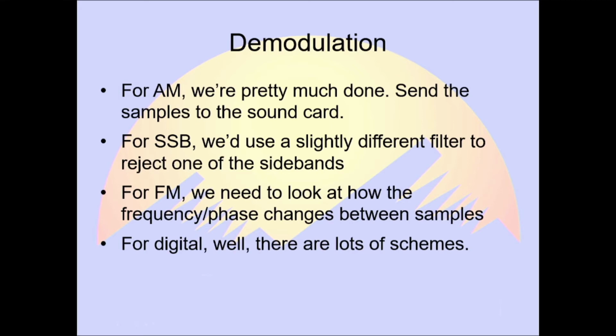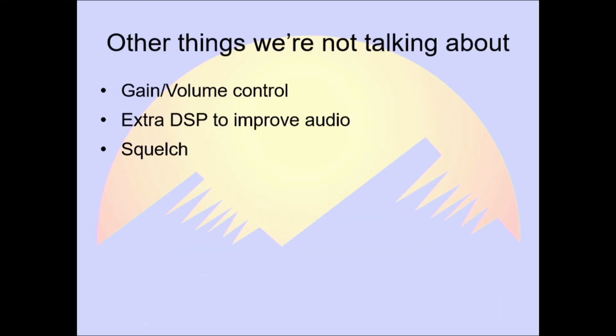So if you want to do it fast, you should go build a chip. That's what programmable logic is for. Then you can program your chip, which is actually very commonly done in SDR. Many of the higher-end SDRs will have an FPGA on the board so that you can do at least some of this processing in hardware or in software-defined hardware. Noticing a pattern here, we can software-define all the things. Cheaper to prototype that way, and you don't have to wait for DHL, to pick on an earlier talk.